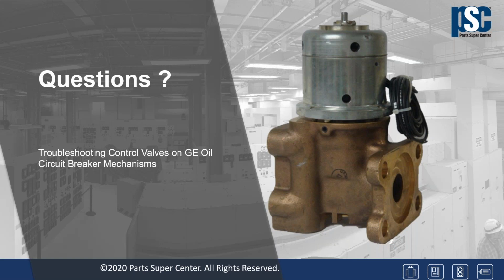So what we recommend, and have been recommending for many years, as most other manufacturers do, is to use a synthetic grease. The one that GE has recommended is a Mobil 28. It's a red synthetic grease, and that's readily available on our website. And we can include that part number in the notes from this webinar.